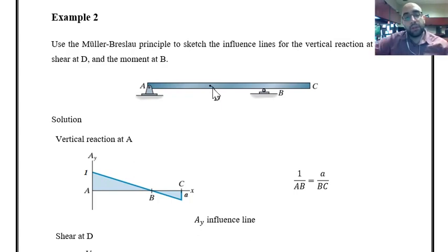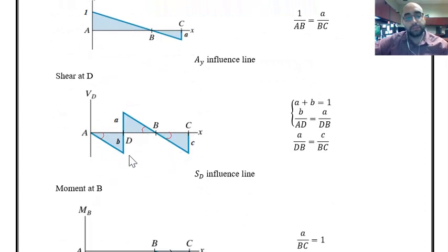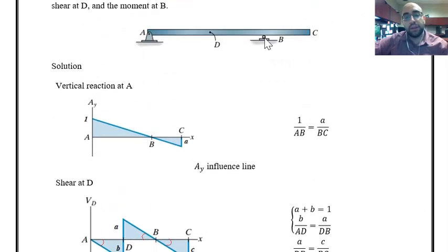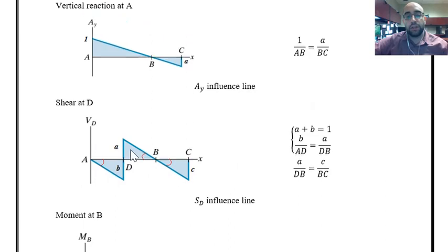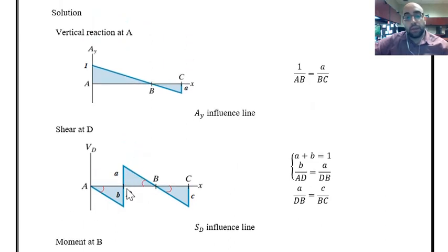So let's apply that unit displacement. This part goes up, this part goes down, and then the two lines are parallel. So I'm going to see those two parallel lines like this. This is the situation. At B, I have this roller support, so the beam cannot have any displacement at B. That's why we have this shape as the influence line for shear at B.